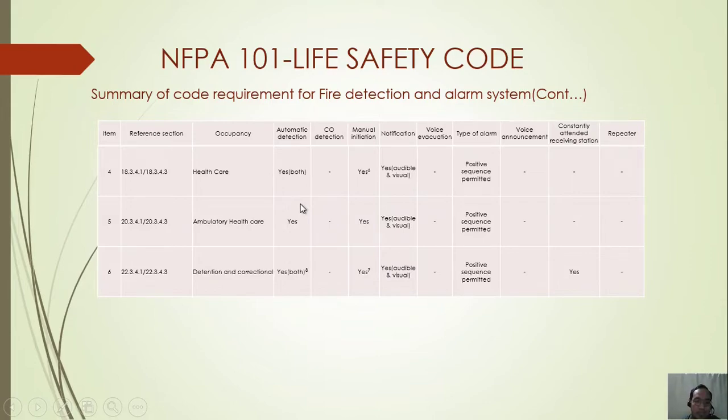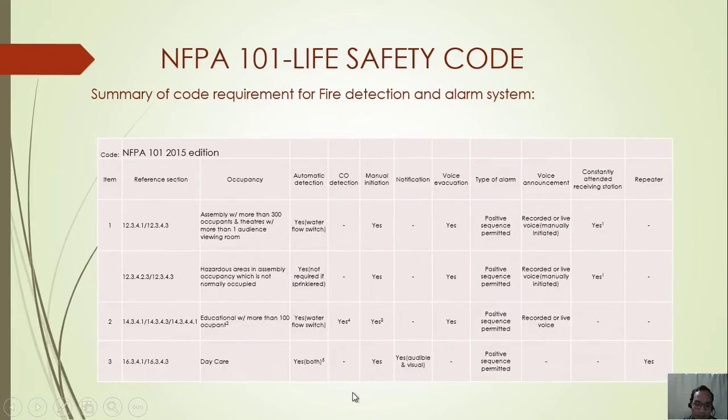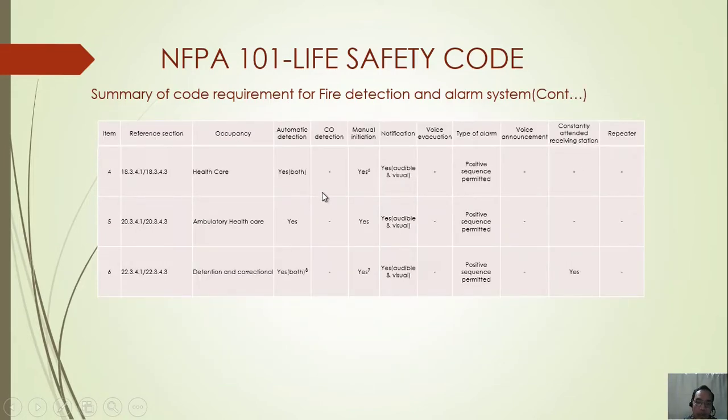Ambulatory healthcare, okay. Also, yes, for automatic detection. When we say yes for both, it means both sprinkler and smoke detection is required. So in healthcare, it's both. I forgot, in daycare also, both sprinkler and fire detector are required.